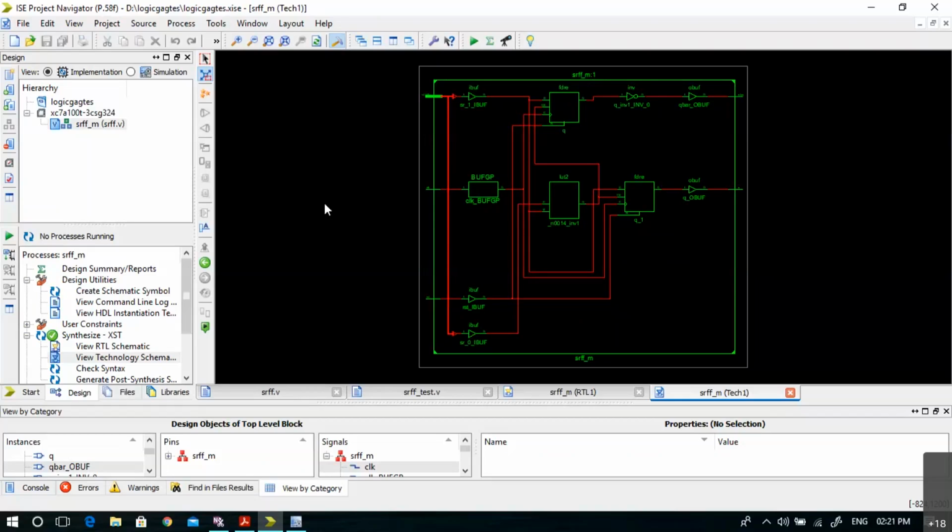So when they developed the synthesis tool, they came to know that a flip-flop as a basic element is required in the library. That's all. So that is the reason we have this flip-flop. But for your question, the answer is you will not be knowing what all elements are present inside the library for the synthesis tool to access, isn't it? You will not be knowing. So you will have to write the code for a given flip-flop. It is up to the synthesis tool to choose whatever is available in the library and connect it together.